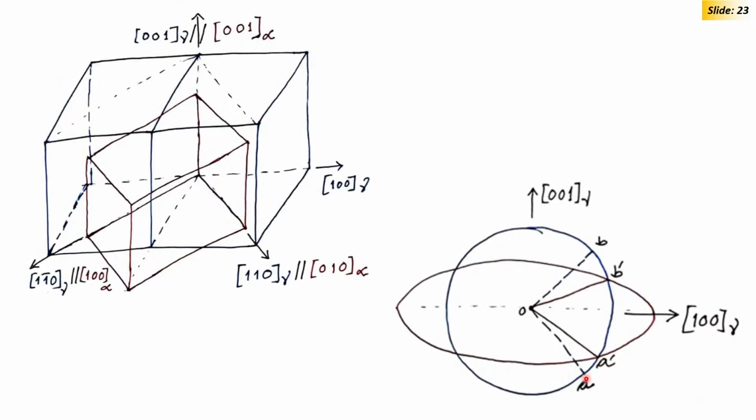So, that means you need a shear which we call Bain strain plus a lattice invariant rotation. The word is lattice invariant rigid body rotation. So, these two things are required, and that is why Bain relationship is not completely obeying the Martensite orientation relationship, because it is not taking into account the rigid body rotation.